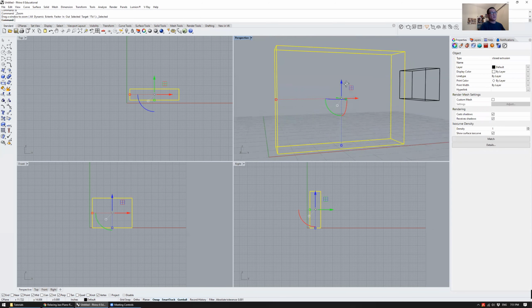So if I'm rotating things around, I select this and use the middle mouse button to zoom select, and it teleports me over there and resets the rotation center to this thing. It will become handy, especially when we start navigating more complex scenes. This helps you move around a bit more easily, okay?